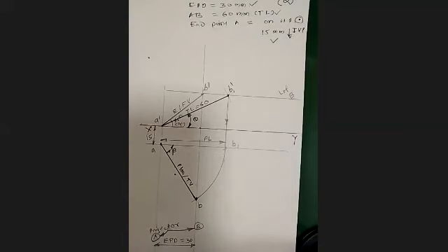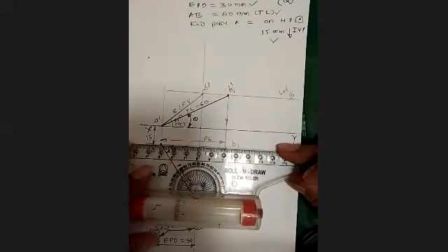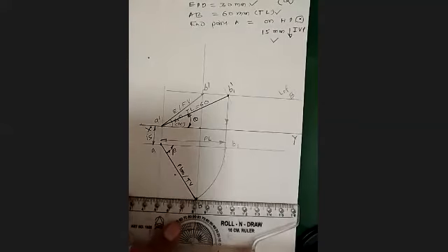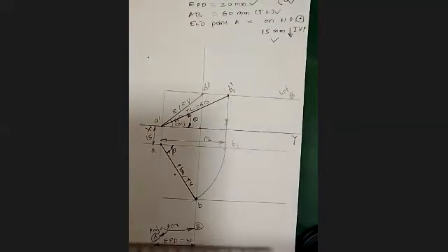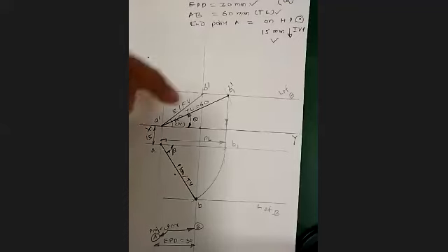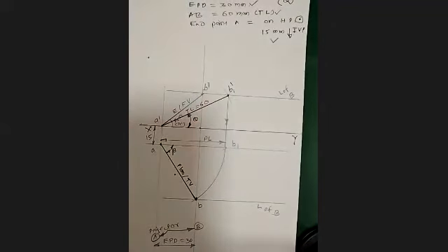Now, as we refer every time, once you get any point, immediately you have to draw the horizontal line through that, and that is going to give the locus of point B. This is going to give the locus of B, right? So right now this answer is almost complete, but the only one thing you can add here, you have true length 60 known to you. Take a distance in compass and cut it, you will get the true length. Okay, this is one way.